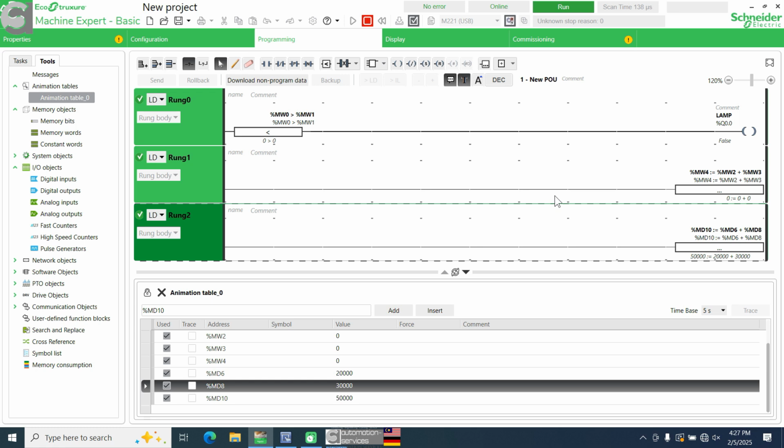Now inside the oven, you set the temperature. Let's say I have an HMI. You set the temperature to 80 degrees. So you must connect a PT100, right?